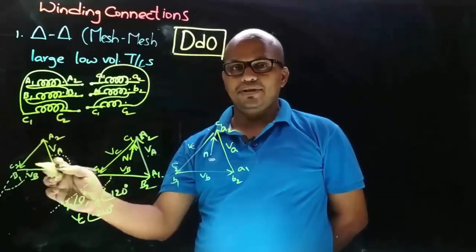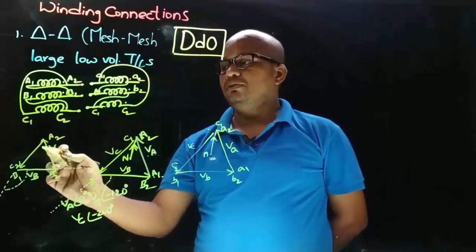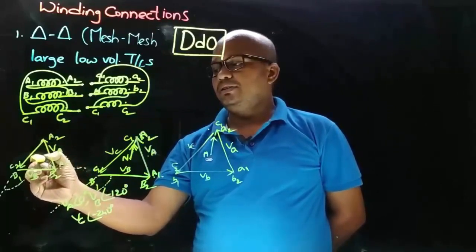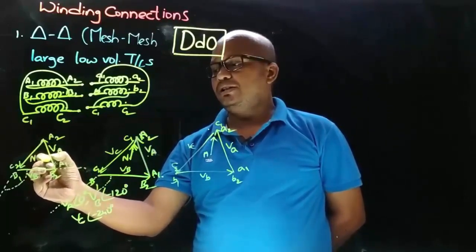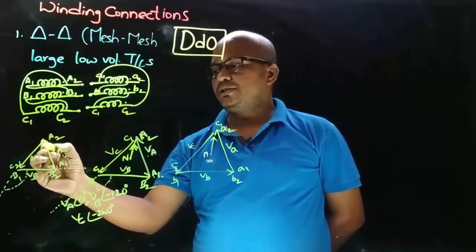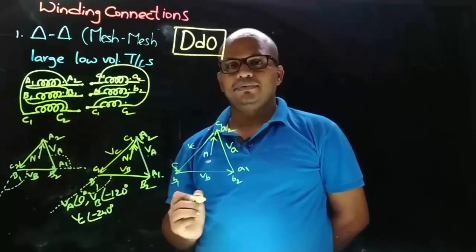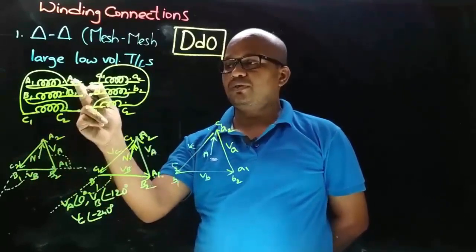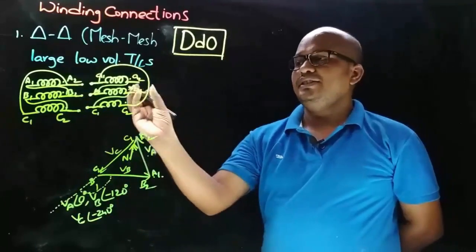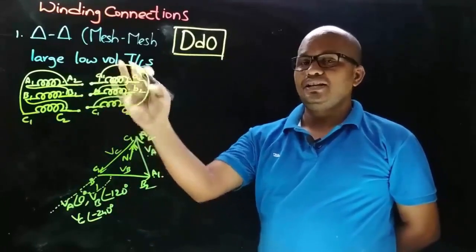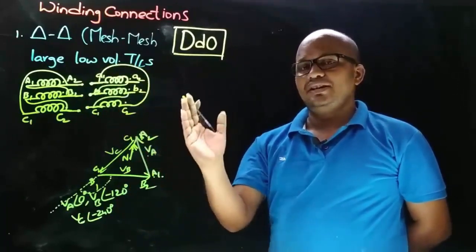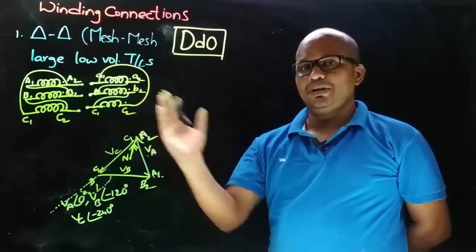And as this is the primary side phasor diagram, so here we are taking the imaginary neutral connection, and the reference voltage is pointed towards capital A2 because we took the connection from A2. So this is what we obtained. Okay, now let's draw the secondary side delta connection's phasor diagram. Okay, so secondary side phasors will be drawn parallel to primary side phasors.